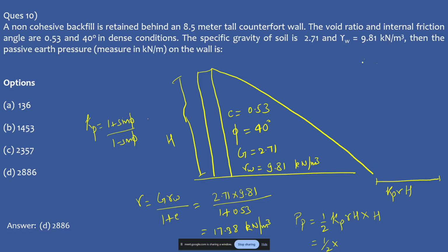No, in that case I had drawn for the soil medium moving towards your passive wall. Here I want my retaining wall to move towards the soil, so the stresses will act in a different direction, right? Backfill is on the right side, sir, therefore it will act on the left side only. The soil medium will have the stress diagram like this.